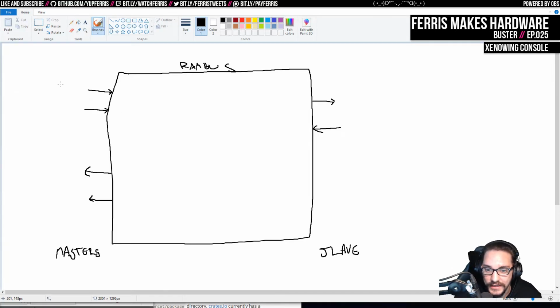So the idea here is that I have two masters. I have master 0 issue, we're going to call this issue and return, and then master 1 issue, master 0 return, master 1 return. So these are the two masters that are issuing reads, and eventually the data will come back through one of these buses, depending on who issued the read.